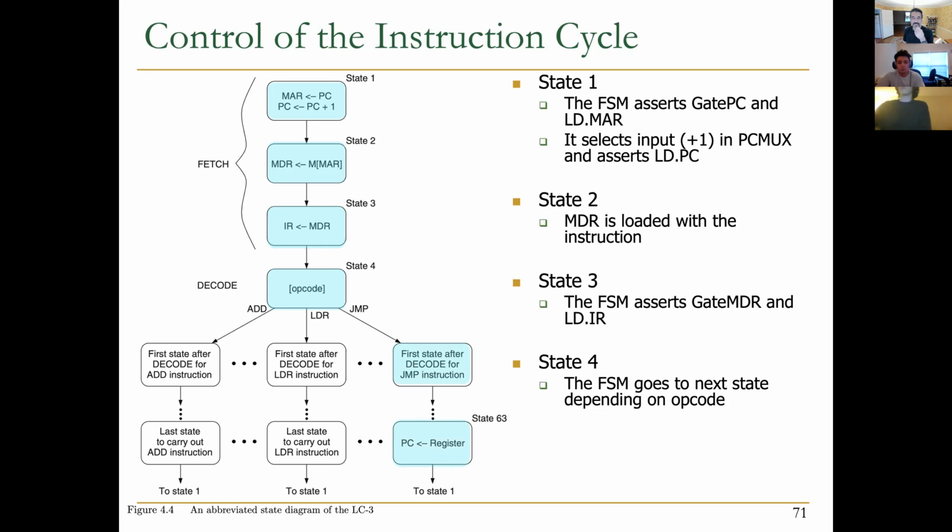So if we assume that this is a jump instruction, then in jump, you know that we need to jump to a particular place in the memory, or putting the particular memory address, loading it to the PC in order to move the PC into this new particular location where it is instructed in the jump instruction, as you remember.